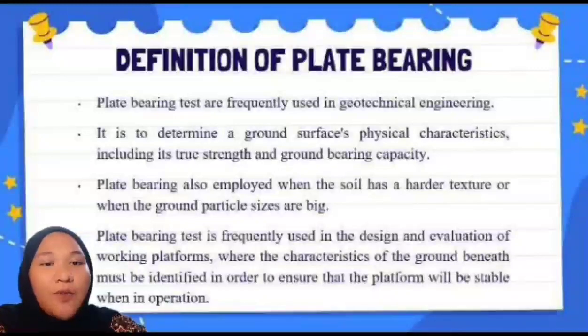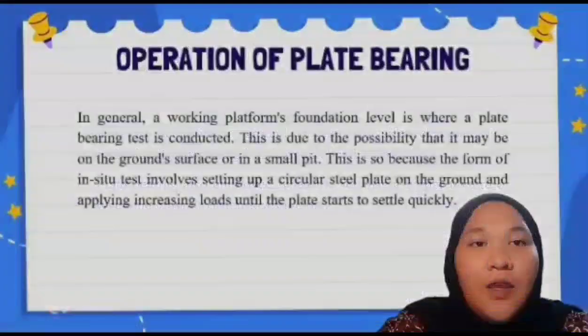Plate bearing is also employed when the soil has a harder texture or when the ground particle sizes are big. Plate bearing test is also frequently used in the design and evaluation of working platforms, where the characteristics of the ground beneath must be identified in order to ensure that the platform will be stable in operation.